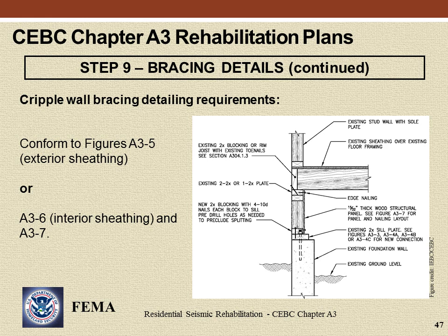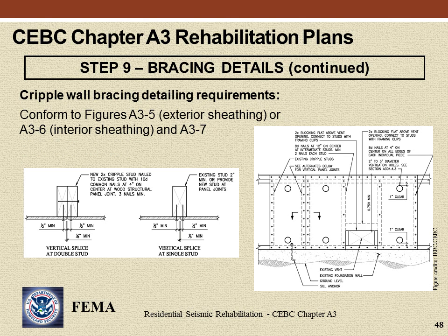The detail also shows a condition in which the foundation sill plate is wider than the studs. As a result, plywood sheathing installed on the interior face of the studs stops on top of the foundation sill plate. In this case, the bottom edge of the plywood is nailed to plywood blocking between the studs. Nailing of the blocking is specified. An alternate approach cuts the foundation sill plate flush with the face of the studs.